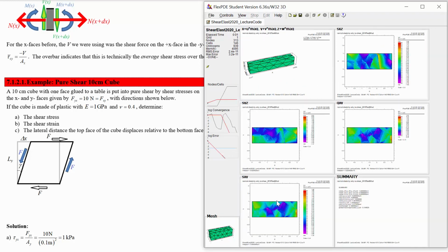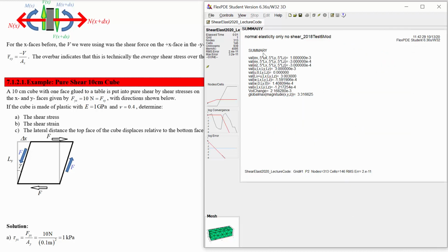Okay, it didn't. It looks like the v displacement has ended up being pretty small because there wasn't any tendency for it to move in v, but it's not quite 0. It's sort of meaningless what the v displacement is. We can officially fix it to have no displacement in y by picking a surface that shouldn't be bothered by having no displacement in y and setting value v equals 0 there. And same thing for z.